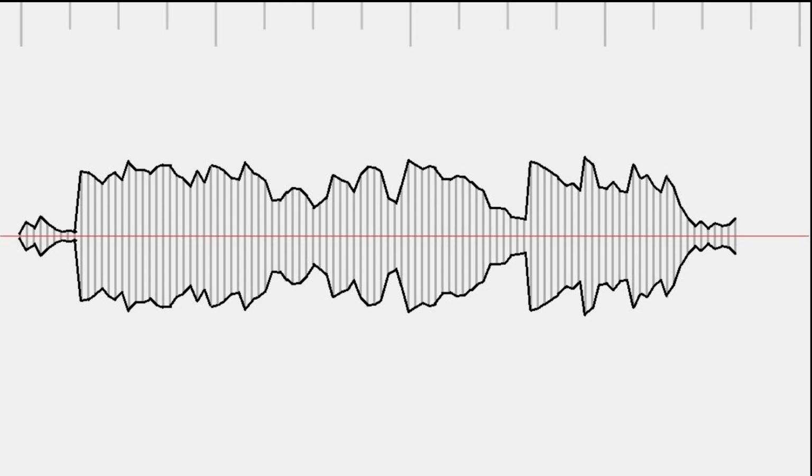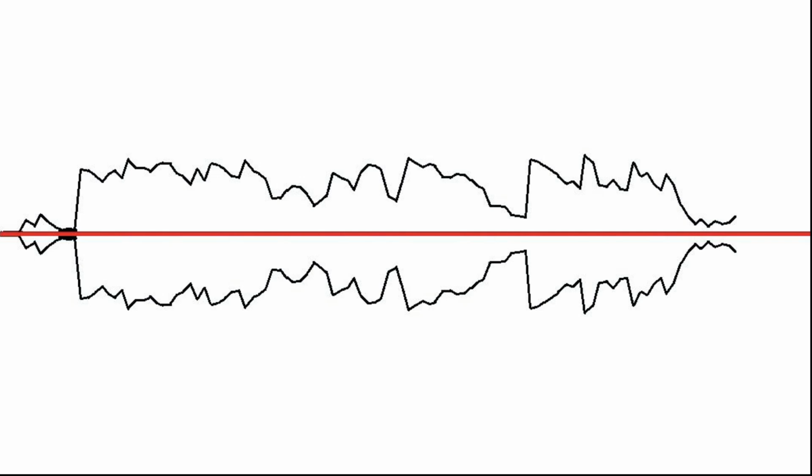To get that, we rectify the radio signal with the diode to get the audio information from the AM modulated RF wave or carrier, because all we need is the envelope, which is the outline of the ends of each tan vertical line, which is shown in black.